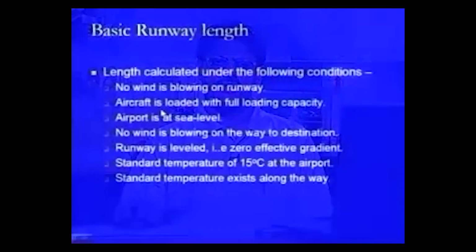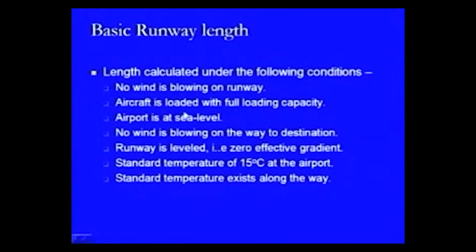Then another assumption is that the aircraft is loaded for full loading capacity. This is another assumption, because it has its effect not only on the speed with which the aircraft will be moving with respect to the propulsion power which is being provided on that aircraft, but at the same time it will also be having its effect on the thickness of the pavement being provided.